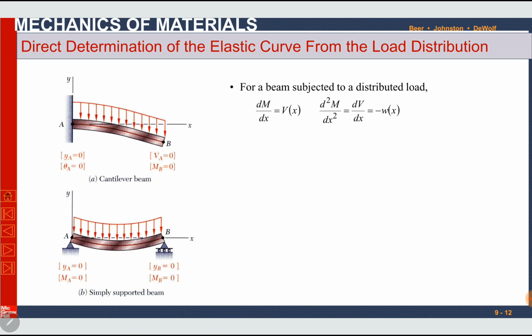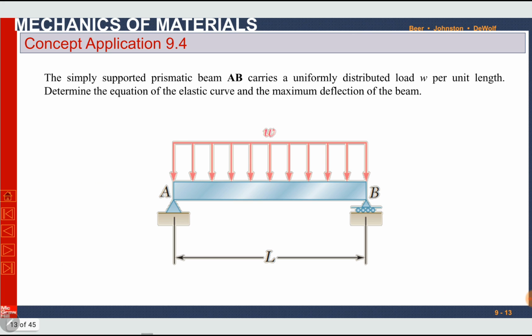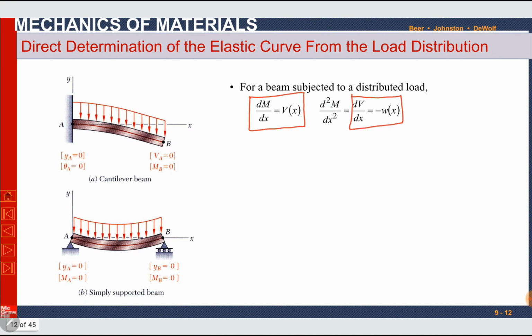Here we have already studied that the differential of moment is equal to shear force. Similarly, we have already discussed in our previous chapters that the differential of shear force is minus the load function. If we differentiate the moment function twice, the double differential of the moment function will be equal to the first derivative of the shear force, which is further equal to the load function, minus w(x). W is a function of x.